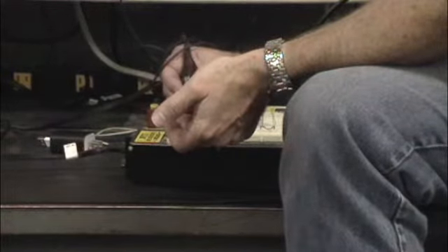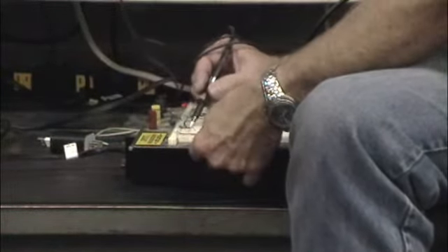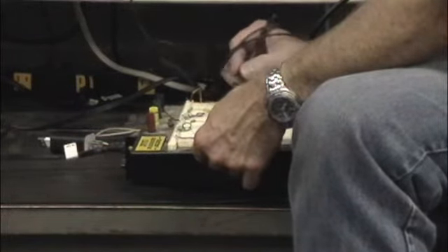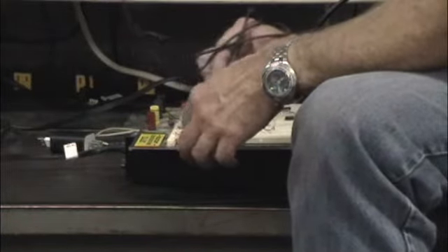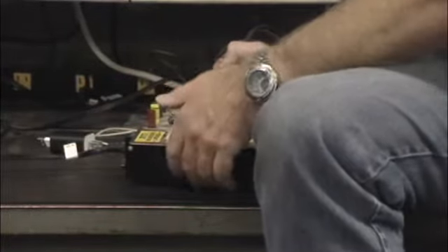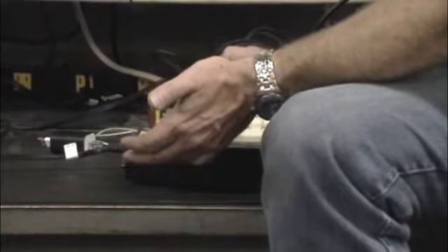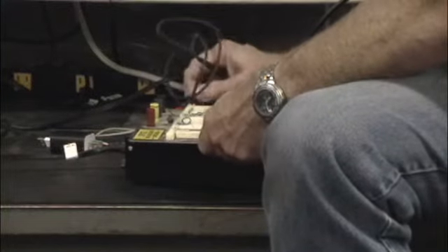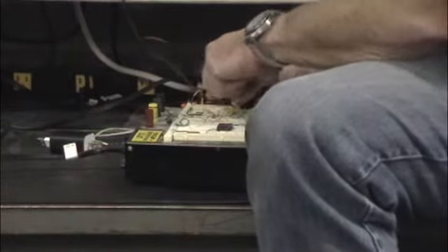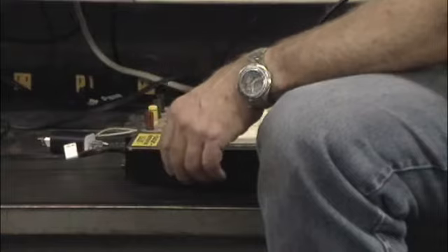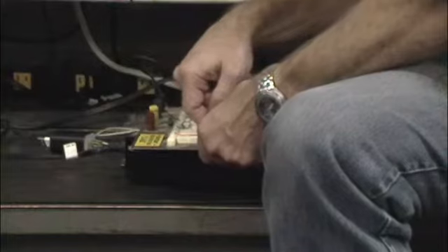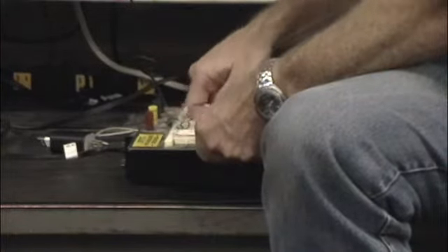So each one of them this way is a wire. And then down the side here, you've got blue and red, and in the middle, blue, red. So all along this is connected 2 lines. Generally, we use the blue as our negative rail, most often ground. Red is the convention for power. So right now I've got 5 volts wired into the red across here, and then I'm distributing it out on different lines here. So I've got power out here wherever I need it. And then I can come in here. This switch, for instance, I can not bend the leads when I pull it out.